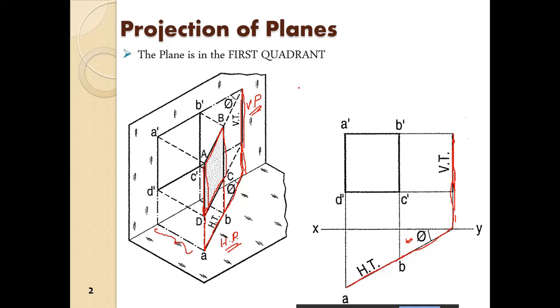Okay. So the dimensions of ABCD, length and height, will be given. At least some values will be given, so we have to work from that. Suppose the height of the plane is given. At that height, we draw one perpendicular. Then we know the edge BC, so we mark the distance BC. From this point, we draw one perpendicular in this manner.